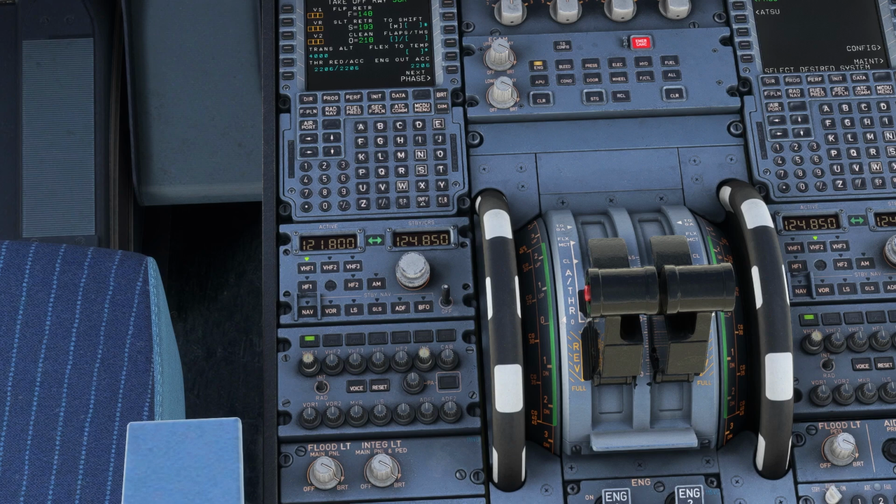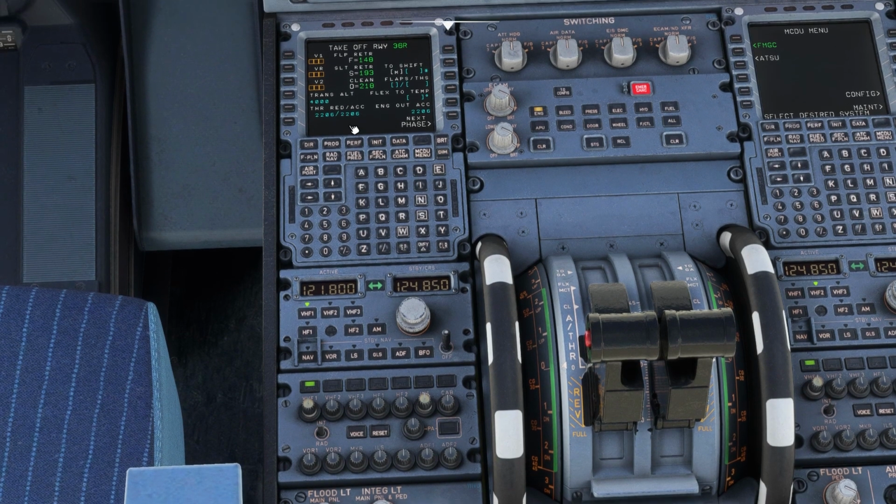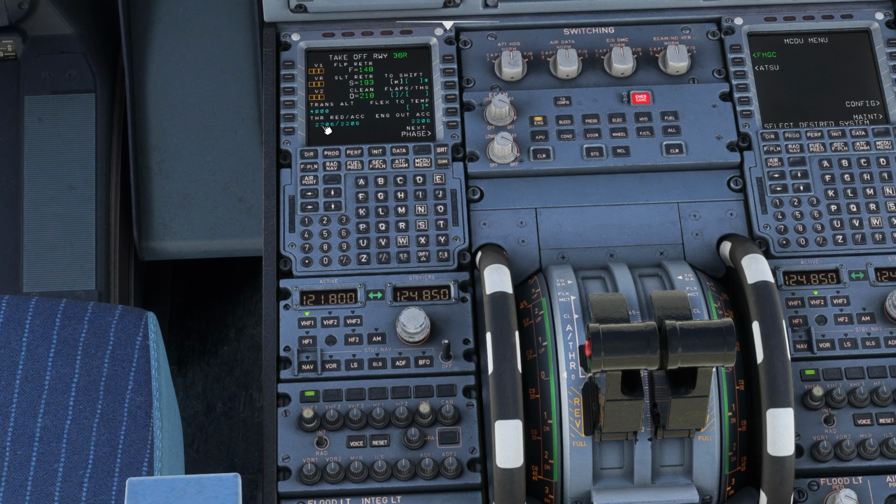So the FMGS, the flight management guidance system, knows that the temperature is very high. So it calculates an optimum thrust power which is less than 100%, obviously not full power, because full power will exhaust your engines and put more stress. It reduces the thrust during the takeoff, and there is enough thrust so that you can lift off. Then you fly at the flex option for 5 to 6 minutes, not more than that. And then at the thrust reduction altitude, you can see coming over here, the thrust reduction altitude is 2206.